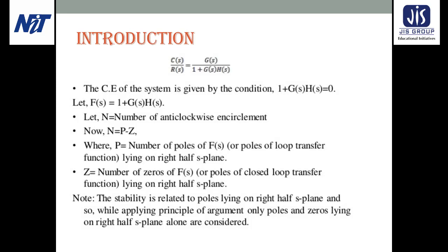The transient response of any first order or second order system can be obtained from the frequency response using the Fourier integral. So, there is also some correlation between the time domain and frequency domain specifications. Time domain performance specifications of a linear system can be predicted by using the frequency domain specifications.